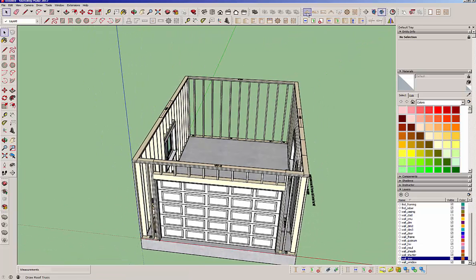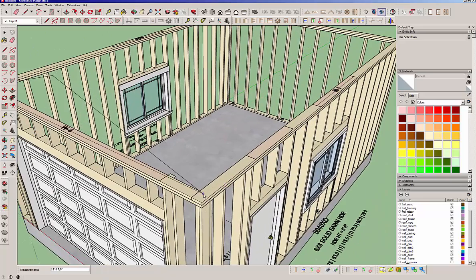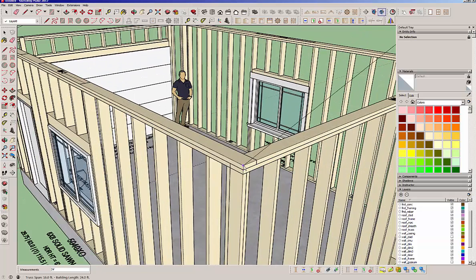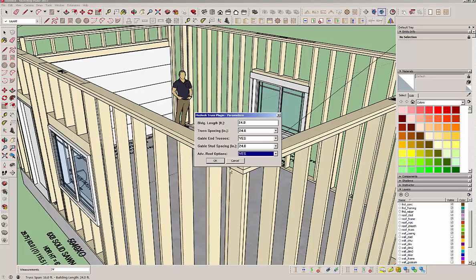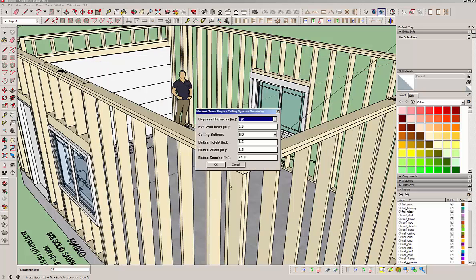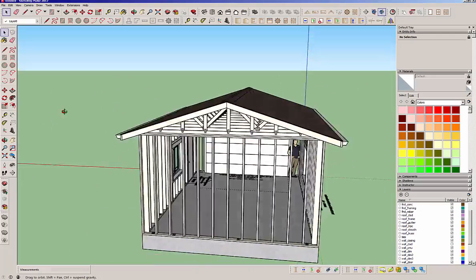Now let's go ahead and add in a truss roof. So, and now we're using the truss plugin to finish this off. And we're going to go here and just hit these 3 corners. Okay, let's go to defaults. And the only thing I'm going to change here is I'm going to enable structural outlookers. And I think everything else we'll just leave as is. Seems reasonable enough. Now it's asking for the gypsum. Okay, yeah, that's fine. Just leave that. And the gutter style, yeah, because we had gutters enabled. Okay, so threw some gutters in there for us. Great.